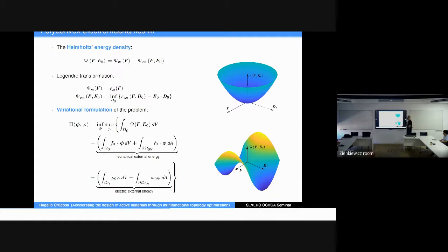All right? As you can see, it is a two-field formulation where the unknowns are going to be displacement and electric potential. So you can imagine your stiffness matrix after when you discretize this, like having like 4 blocks: mechanics, mechanics and phi, and x, phi. All right? Cool. So polyconvexity brings benefits not only from the constitutive standpoint. I didn't justify before the selection of or the satisfaction of the Legendre-Hadamard condition. I should have said it before. Why do we want our energy to satisfy the Legendre-Hadamard condition?